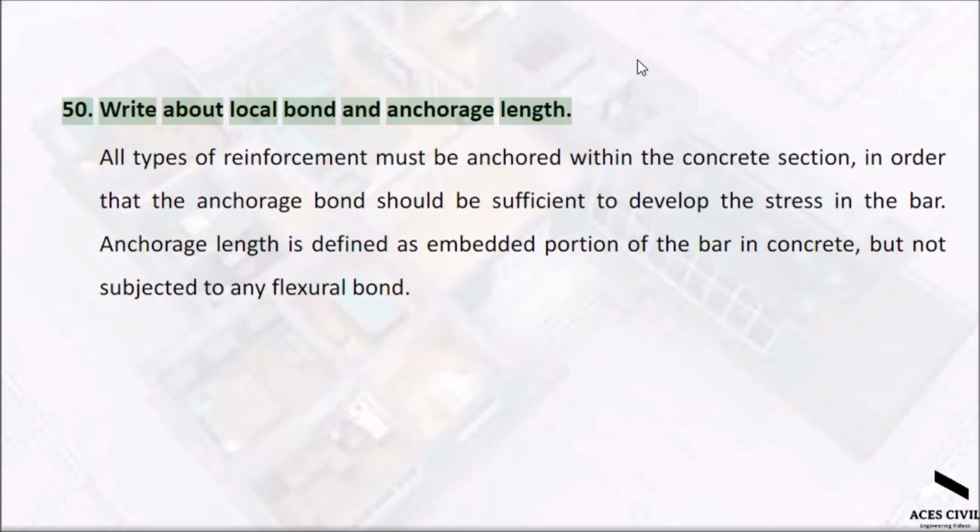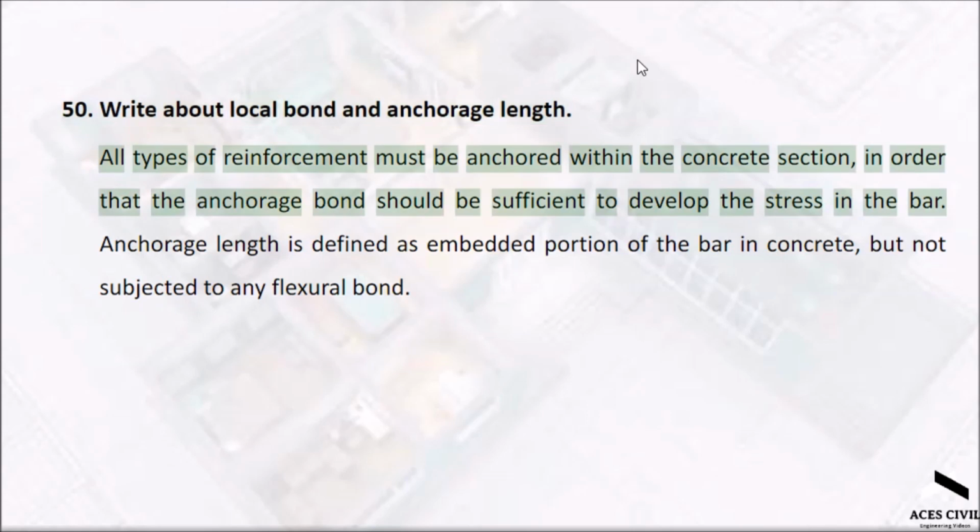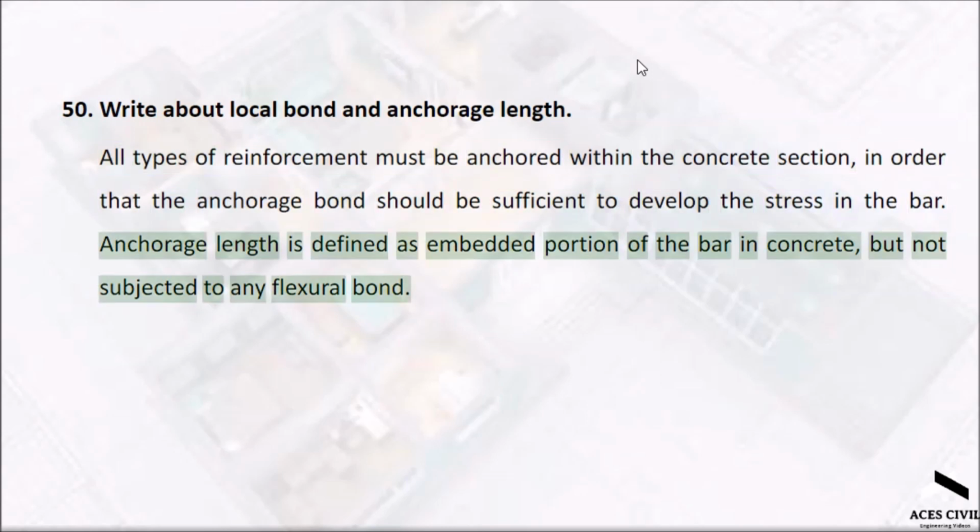Write about local bond and anchorage length. All types of reinforcement must be anchored within the concrete section, in order that the anchorage bond should be sufficient to develop the stress in the bar. Anchorage length is defined as the embedded portion of the bar in concrete, but not subjected to any flexural bond.